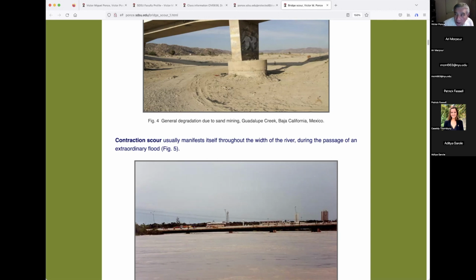Admittedly, the geotechs use very low factors of safety. That is true. 1.5 is typically geotech. Why they did 1.3 in here, I don't know. And on top of muck, I would not have done it. As a matter of fact, I would have never done that kind of situation, which is a vertical wall, because we know a vertical wall can tip, which does not happen in an embankment.